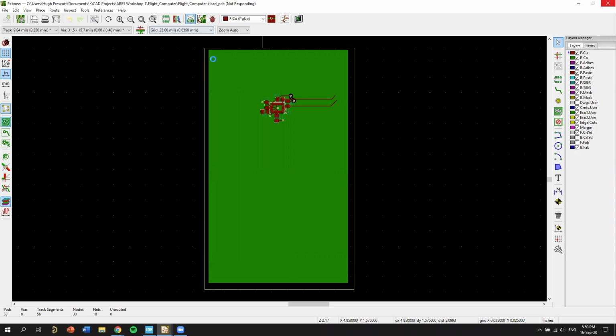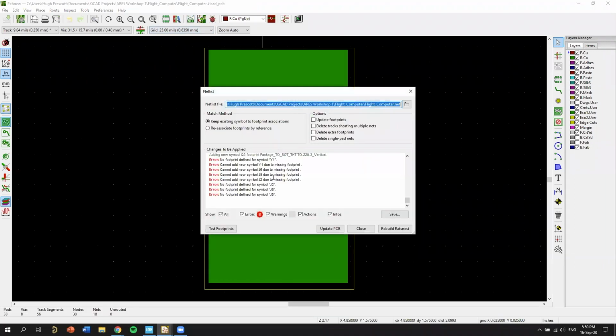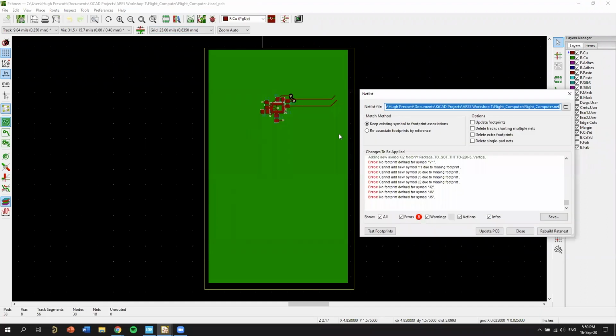We did this the other way, but I'll go through it again. You define your edge cut. So this yellow line is telling the program where the outside of the board is. And then this big green layer is a big copper pour, which is all considered ground, so you can connect things up easily.